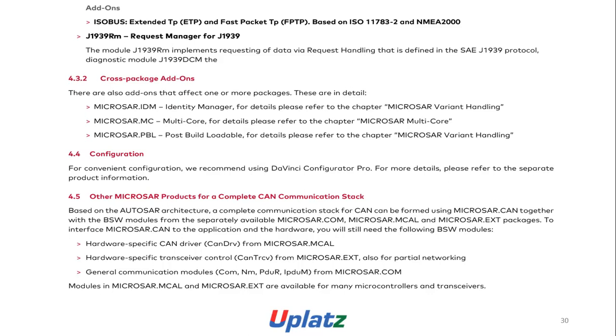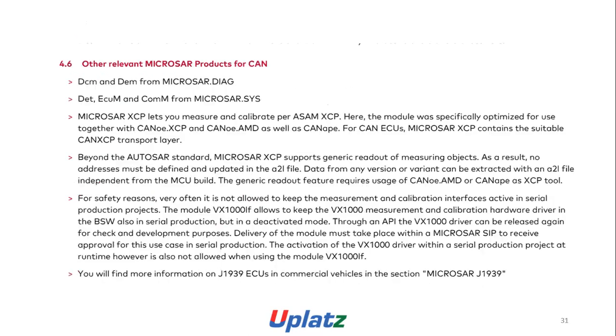You will need the following PSW modules: hardware specific CAN driver, CAN DRV, from MICROSAR MCAL; hardware specific transceiver control, CAN TRCV, from MICROSAR EXE, also for partial networking; general communication modules COM, NM, PDUR, IPDUM from MICROSAR COM. Modules in MICROSAR MCAL and EXE are available for many microcontrollers and transceivers.